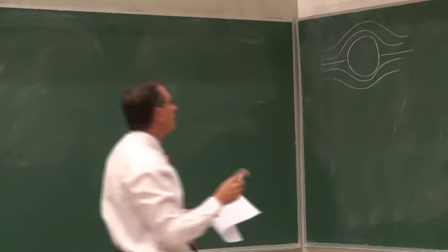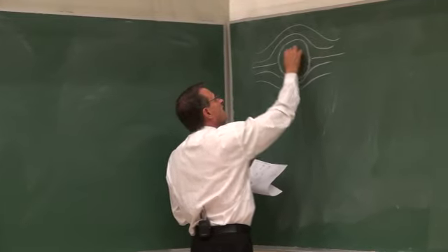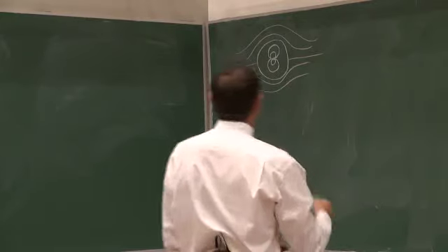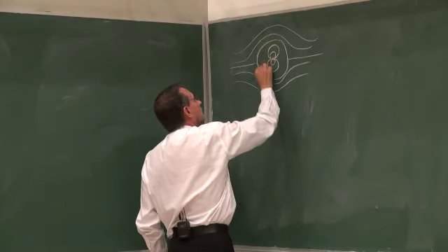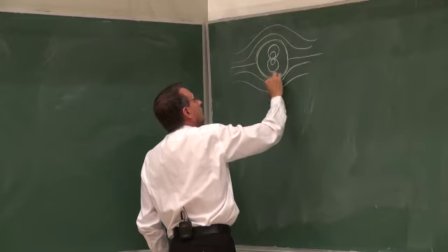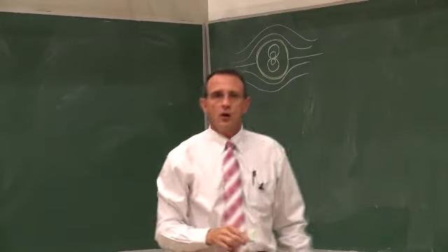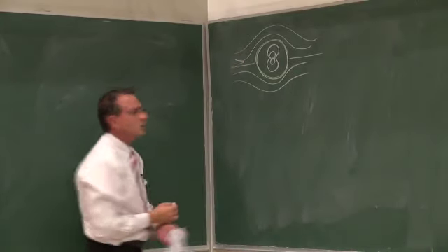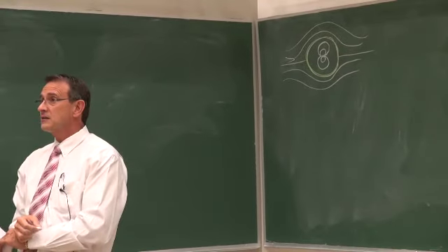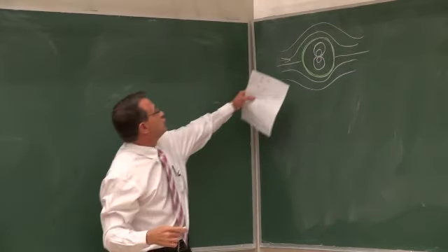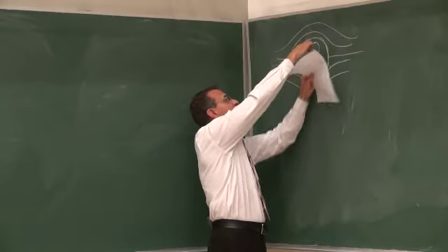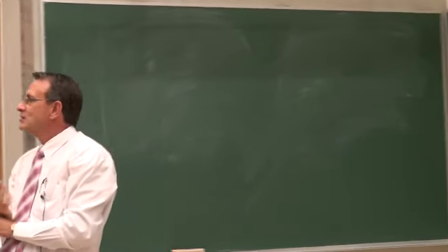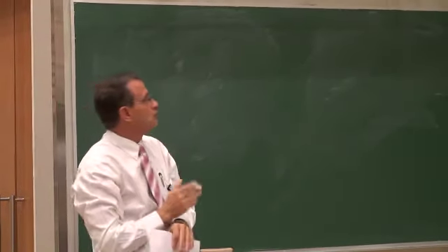That also does this. I specifically drew the cylinder first so that it's easy to identify. Now what building blocks would give us that flow field? I think it was a uniform flow field and a source and a sink just next to each other. So that is what generates that flow field.